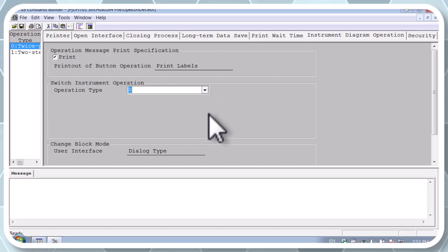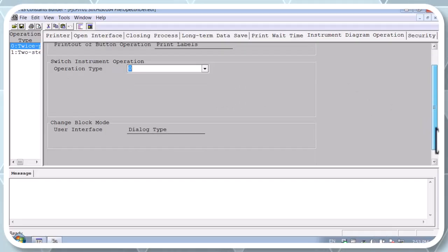And next one is the two-step operation. The two-step click selects the object, and when you select the object, a confirmation window appears, and the operator must confirm before the command is sent. For example, you click the pump start, and a confirmation appears with a question sign, and you use it to run your pumps.